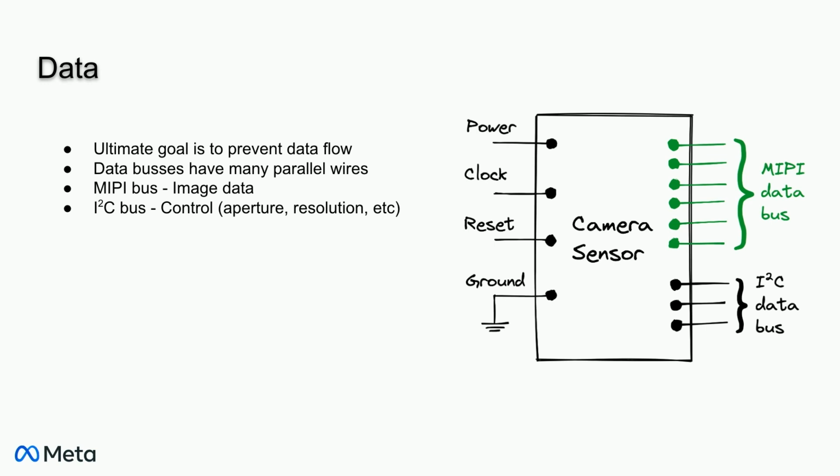So disabling an electrical bus means putting a gate or a transistor on each of these wires so we can turn them off simultaneously. And this increases complexity. Also, these high-speed transmission wires for data are often very sensitive to changes in electrical properties like impedance. So it's not so simple to simply turn them off and add components in the middle.